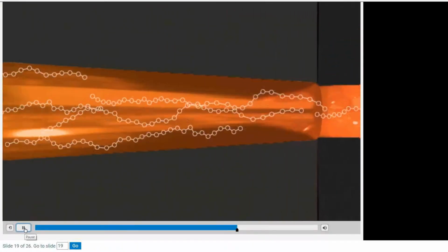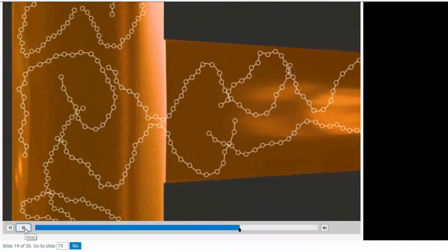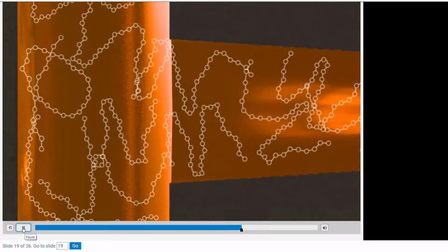As materials flow, their molecular chains align. When they stop flowing, the molecular chains return to their natural coil-type structures. When polymers go back to their natural relaxed molecular state, the molded part shows very little molded-in stress, and therefore less potential part warpage and higher dimensional stability. If the aligned molecules are frozen during flow, their alignment is maintained, resulting in flow-induced molded-in stress. In clear parts, this can be evaluated as birefringence.